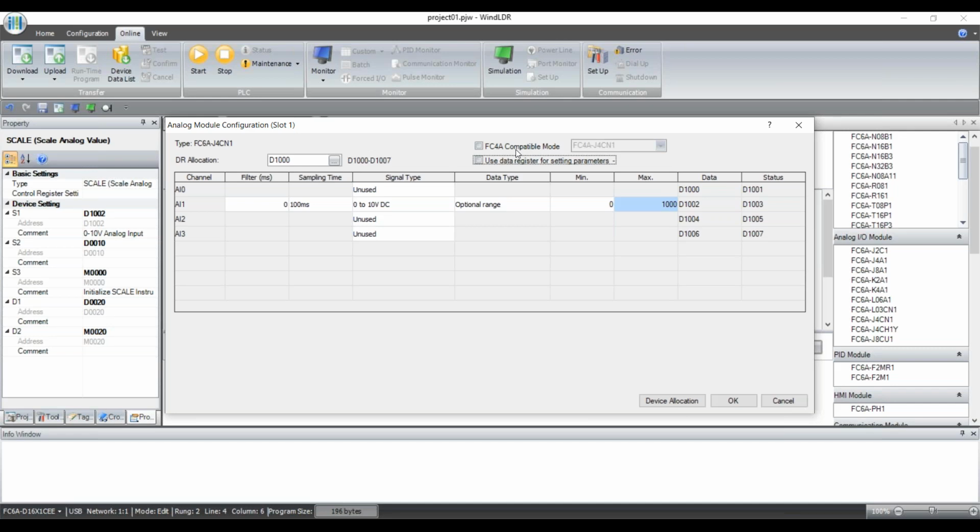okay? So in order to be able to process that, we needed to make sure that we could increase the speed at which the internal communication bus, we slap a card on there, how fast that thing could send data back to the PLC, right? It's no good if we've got a slow card, if we can do 2000 IO if the card's too slow. So unfortunately, we had to change that.